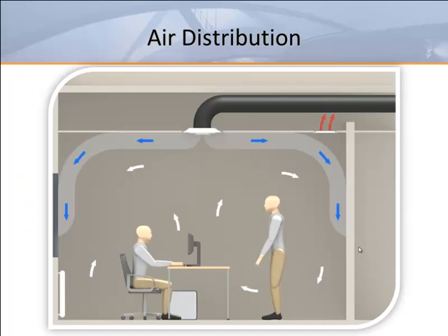Conventional overhead systems provide comfort through room air mixing. For this reason, these systems are also known as fully mixed systems. In a typical cooling application, 55 degree Fahrenheit supply air is delivered from a ceiling diffuser or a high sidewall grill. The mixing created by the outlet discharge jet results in room air motion. This so-called secondary air motion is due to the entrainment of room air into the supply jet where mixing occurs.